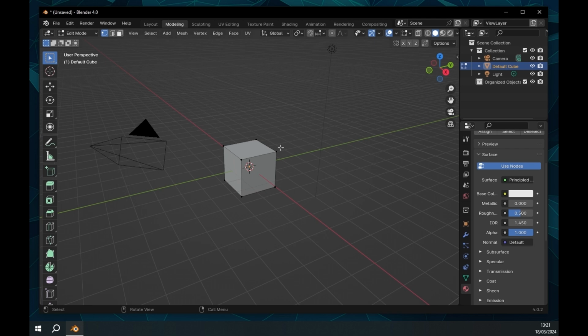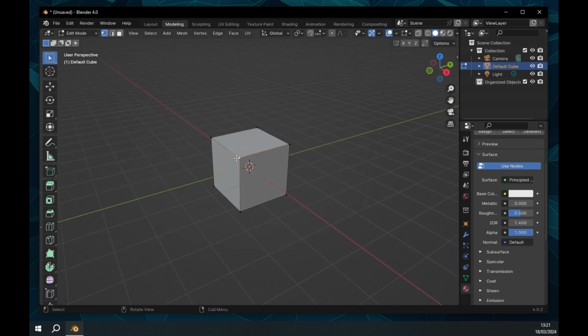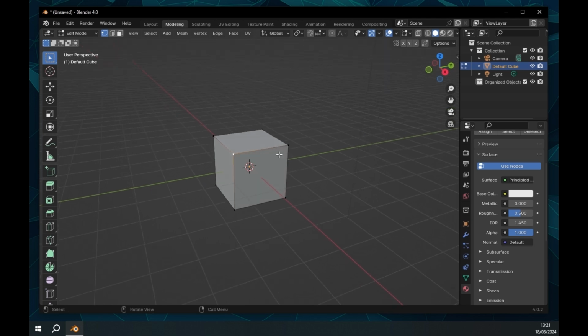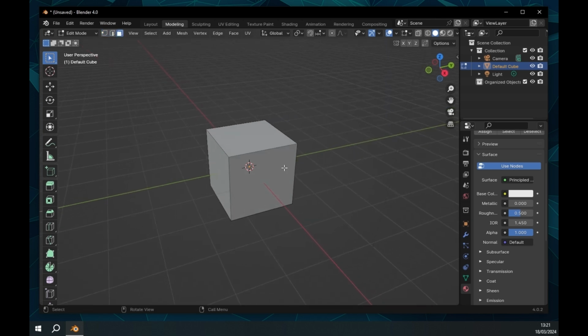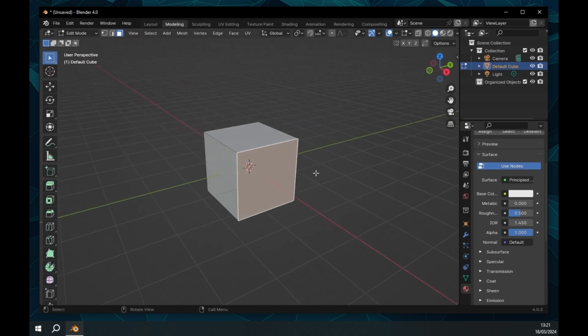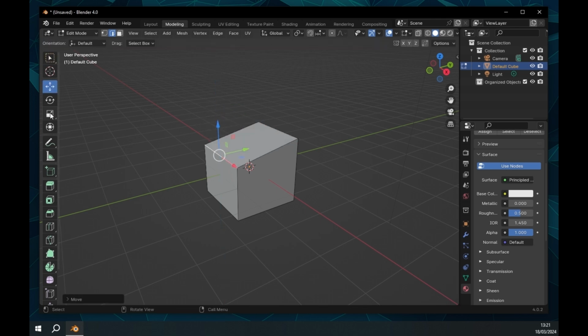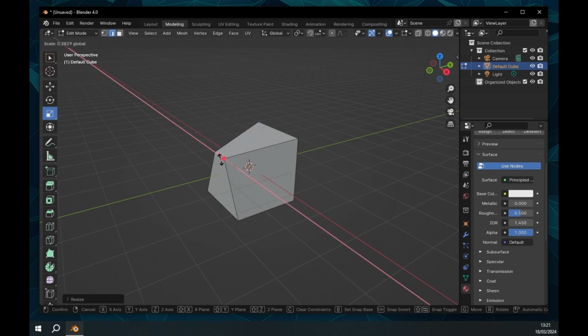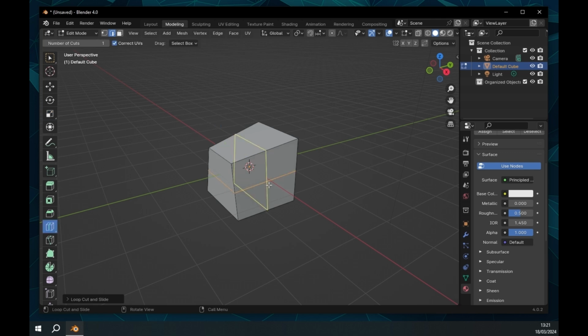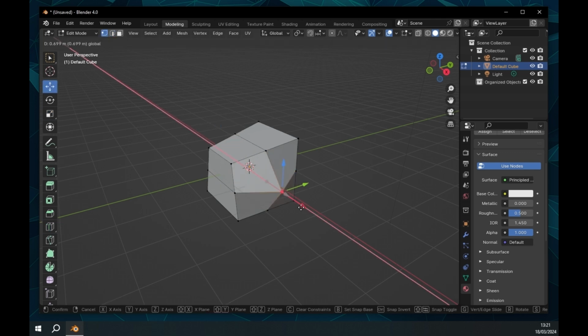Edit mode is where you can make direct changes to your 3D model's mesh. You can press the keys 1, 2 or 3 to swap vertex, edge or face selections respectively. You have at your disposal an array of essential tools such as cuts, extrusions and vertex manipulation, enabling precise adjustments at every level of detail.